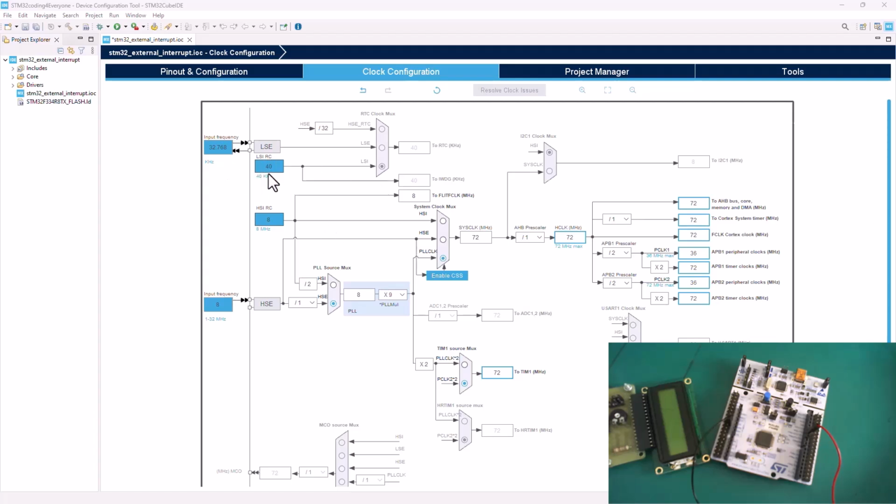Now, this really depends on application. Most applications, okay, if you are just running a simple application, you can also use this, because this RC basically means you're going to have a resistor and a capacitor to basically set your timer for your external clock oscillator. So now the accuracy is not the same as having your crystal oscillator running here, right? If you select